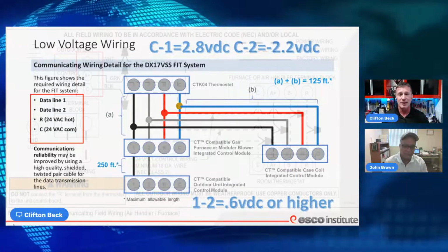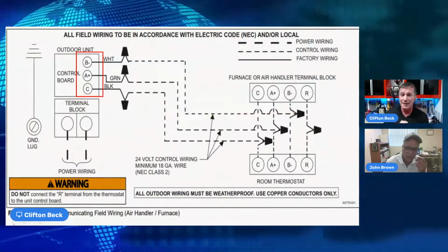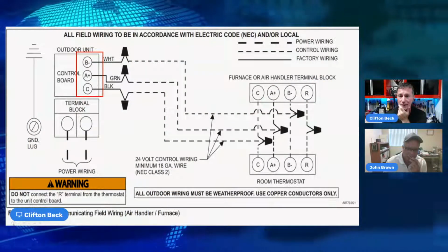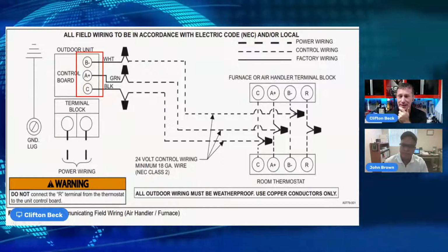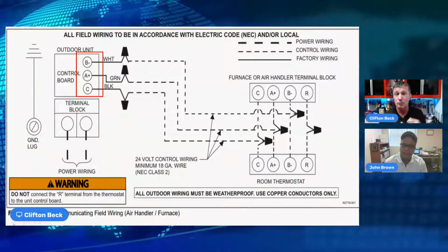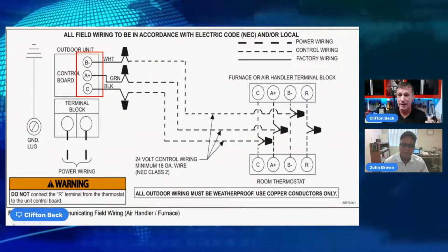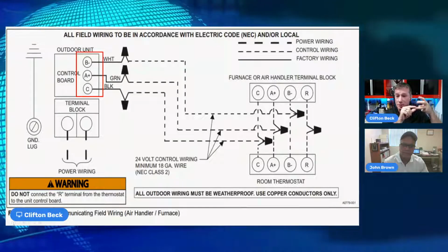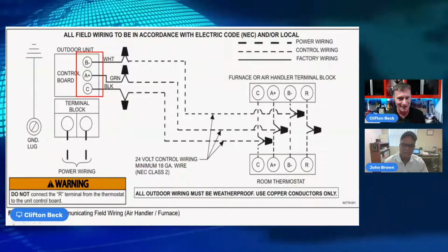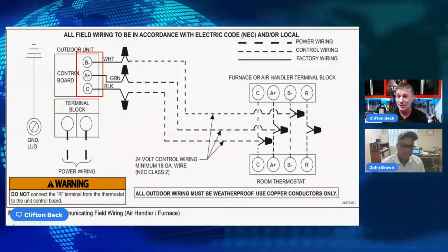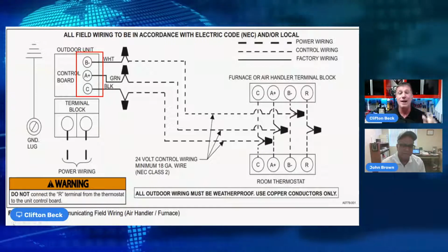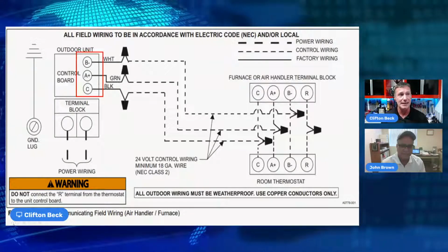Well, let's look at another manufacturer. If I look at this wiring diagram, I go, my goodness. I have another positive and negative signal, and I'm using a common, so a ground reference point. So this particular manufacturer is using 3 wires. It is using common, which is a grounded common, so that is our ground reference point. It has a positive signal on A in reference to ground and a negative signal on B in reference to ground.